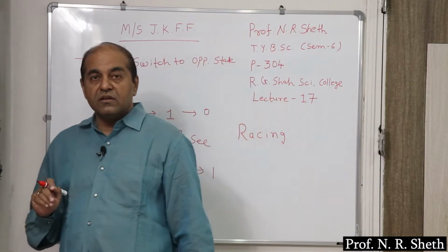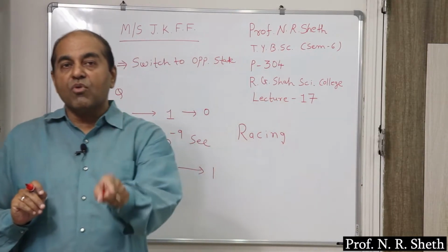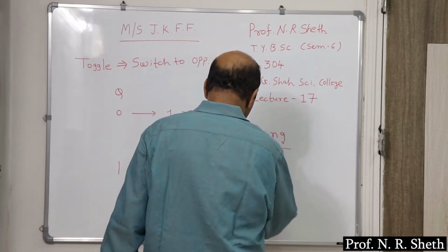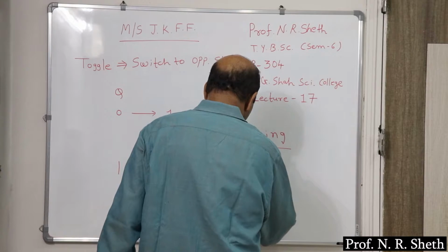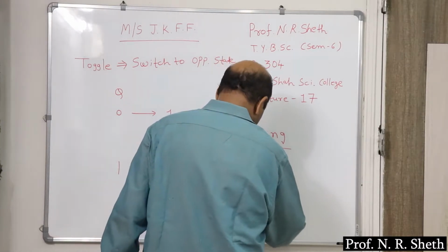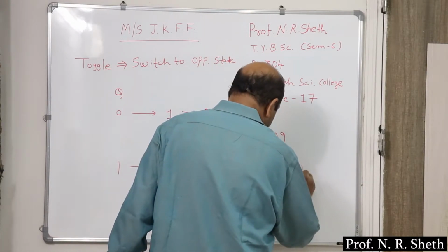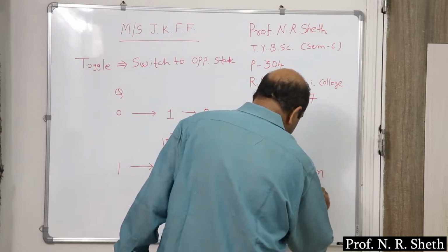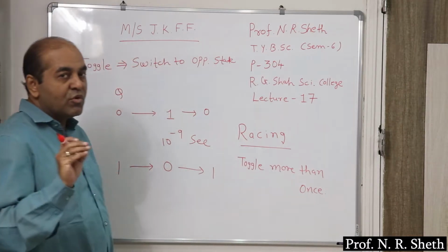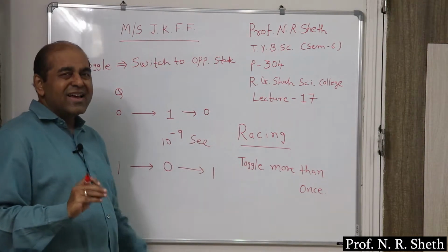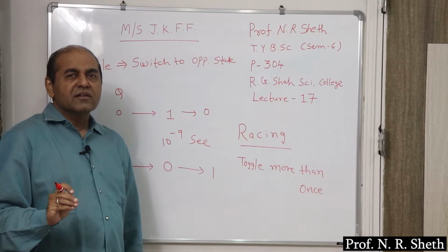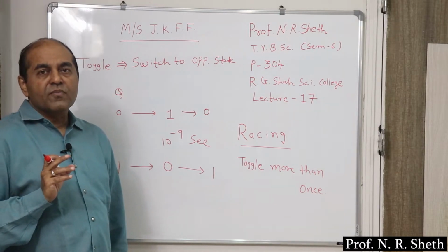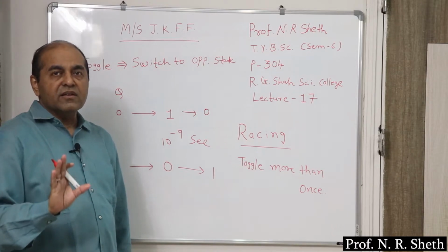What is racing? Toggling more than once, that is racing. Toggle more than once is racing, and this is the only disadvantage of JK flip-flop,